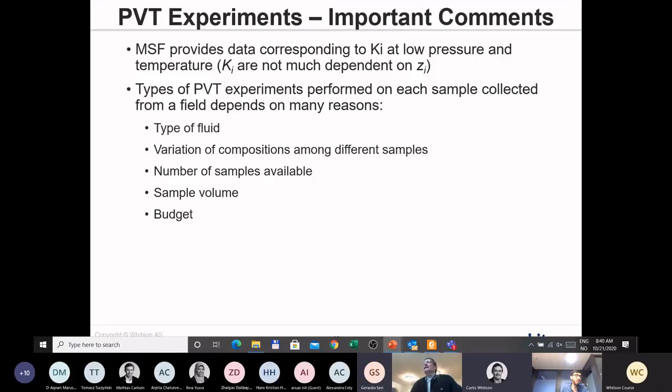Okay. But what he's saying is that it doesn't usually have a big effect on the K values. The only exception to that really being near critical oil DLE. In a near critical oil DLE, in the first step, you may remove half of the solution gas, so the composition goes from being a critical composition with K values converging to 1 to being something that's far removed from critical. Okay. Just slightly below it. So that's probably the only exception to the rule. Okay. Thanks.